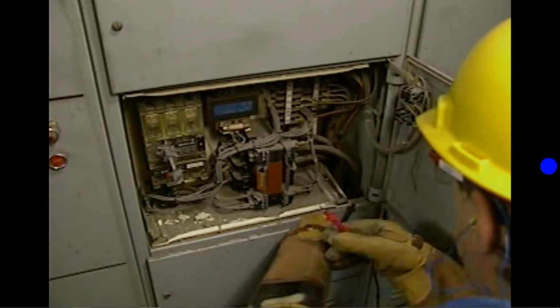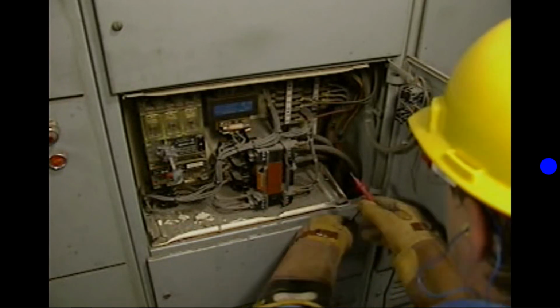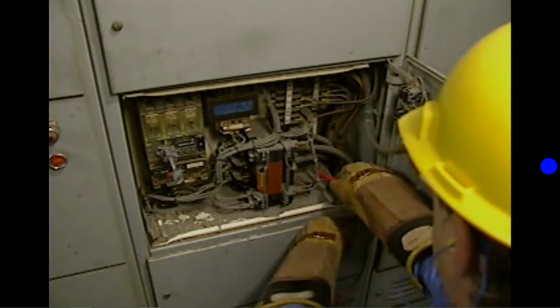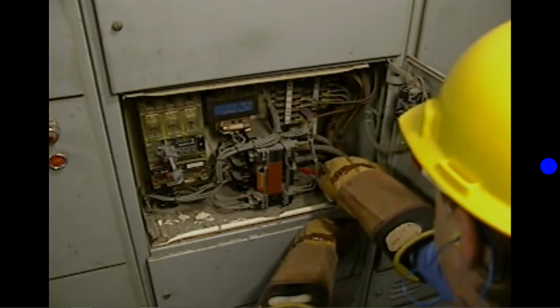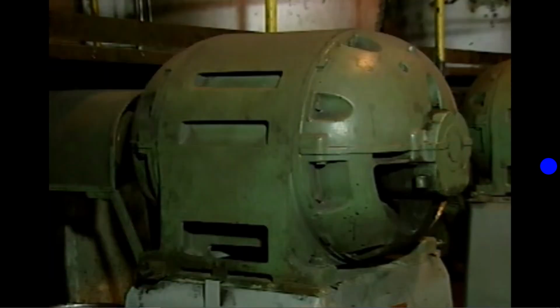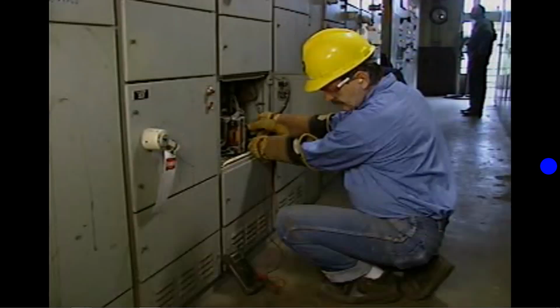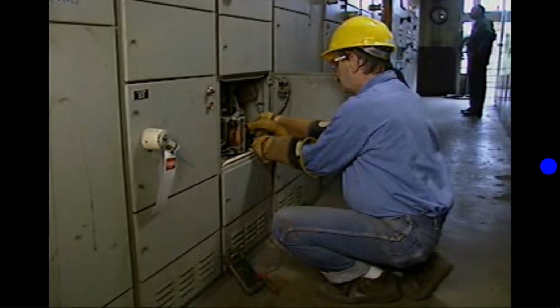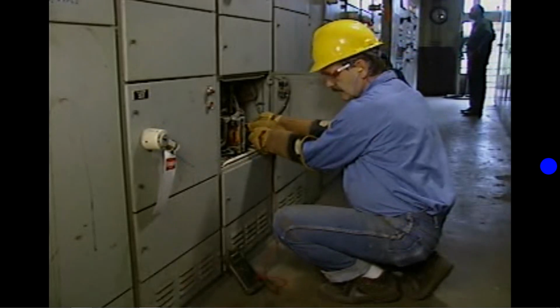For example, the controller's contactor and overload devices can be checked to make sure that they're operating correctly. If the controller is operating correctly but the motor will not run, then the motor leads from the controller to the motor and the motor itself will need to be checked. If the motor leads check out, the motor should be de-energized at the motor controller and the controller should be locked and tagged according to company procedures.